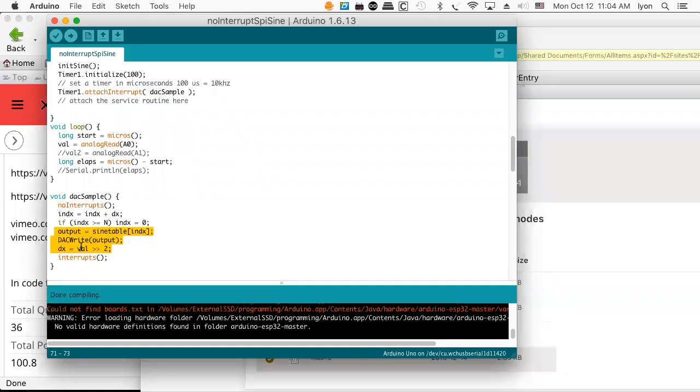And here is a value which I got from my analog read over here in the loop, and that'll update whenever it updates. I mean, that might take time. It might be in a wait mode, waiting for an analog device to read. I don't know how long it will take to do the analog read. I think the default is 9.6 kilohertz. Whatever it is, I don't care because I'm going to make sure that my sampling for the audio occurs on time without interrupt every 100 microseconds.